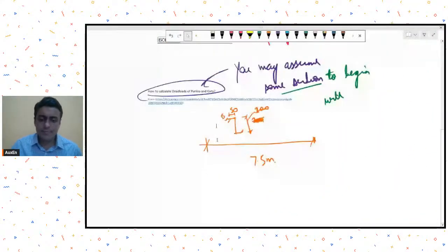Yeah, so I was telling that a 200 mm deep section for around a 7.5 meter span, having a thickness of around 2 mm or even 1.8 mm, may be good enough for a 7.5 meter span, maybe with two sag rods. So if you know this section, you can easily calculate its self weight, isn't it?